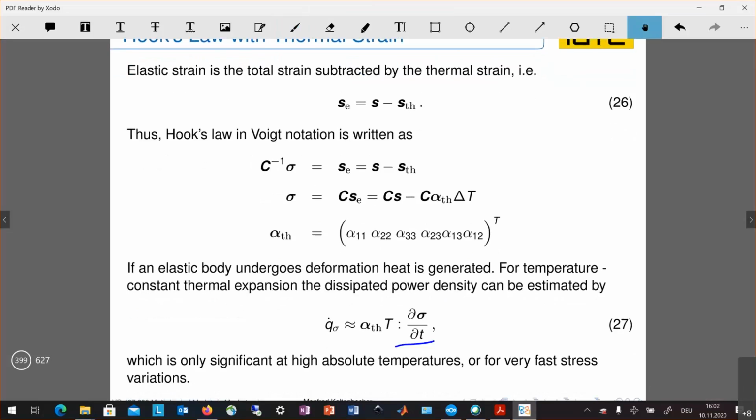But for most cases, this is not necessary to be taken into account, which means, especially in our application, that we first can compute the temperature field, and then in the next step, we can compute the mechanical deformation of our body of investigation according to this temperature field with the thermal strains coming up due to the temperature distribution within our body.